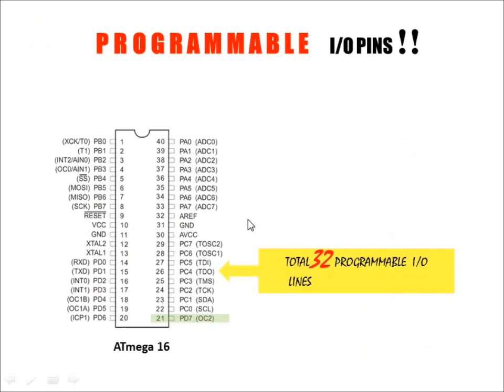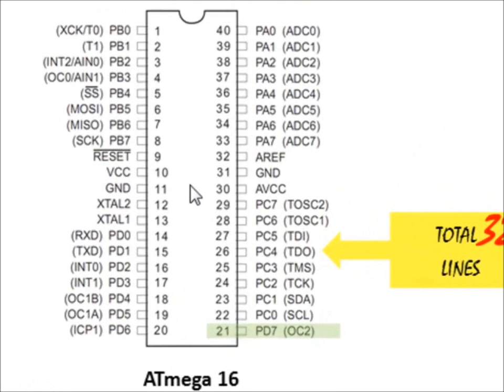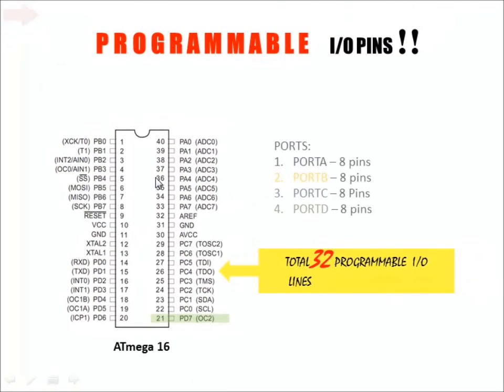Now let's have a look at the pin diagram of the ATmega16 microcontroller. It is a PDIP package. As you can see, it has a total of 40 pins, 32 of which can be programmed as input-output pins. These pins are programmable. You can either set a pin as an input or as an output pin. All the input-output pins of AVR microcontrollers are divided into groups. These groups are called ports. Each port consists of 8 input-output pins. Thus, ATmega16 has a total of 4 ports labeled as port A, B, C and D.